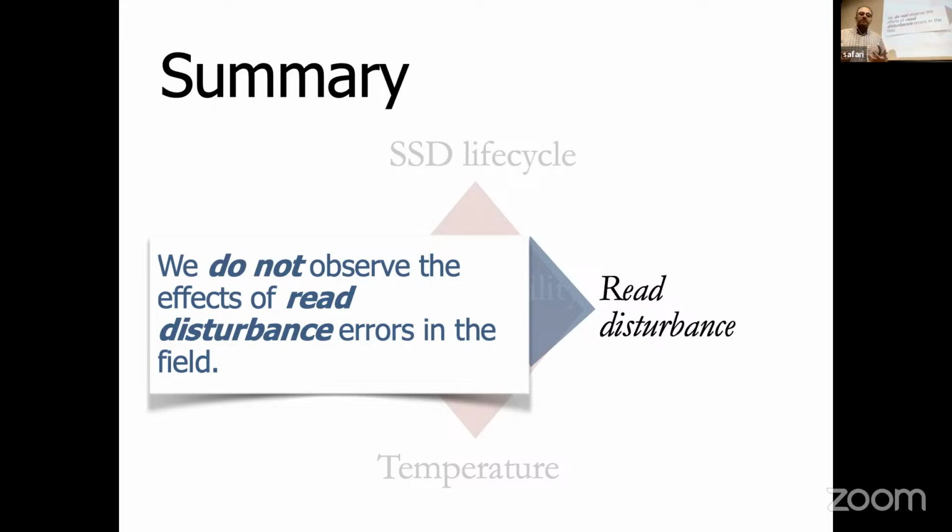I would say that a flash controller is a lot more intelligent than a DRAM controller, because the DRAM controller is not doing all these intelligent mechanisms that we were discussing. That was also part of the beginning of this course, where we showed that by making the DRAM controller more intelligent, we can fix many scalability issues of DRAM. But flash controllers are quite advanced, and they implement many mechanisms to fix the errors.